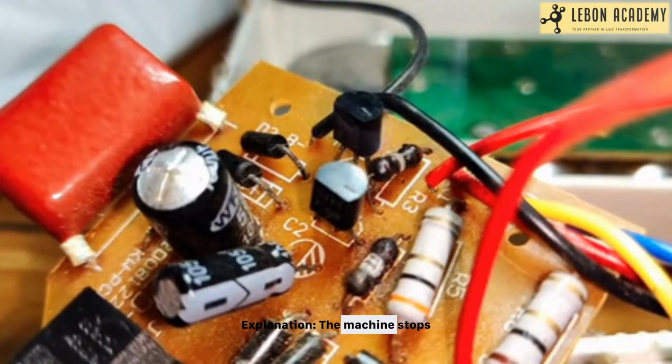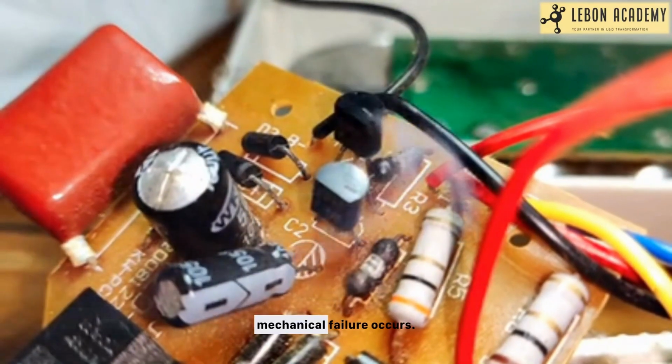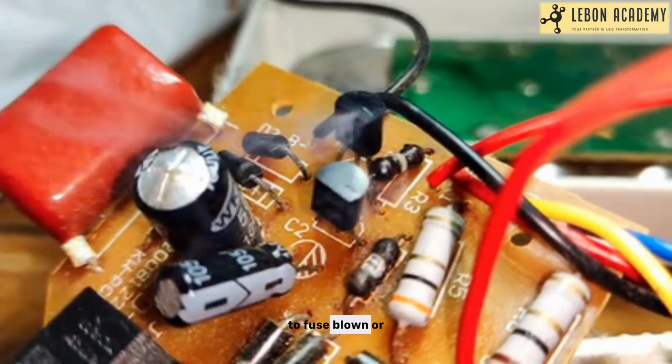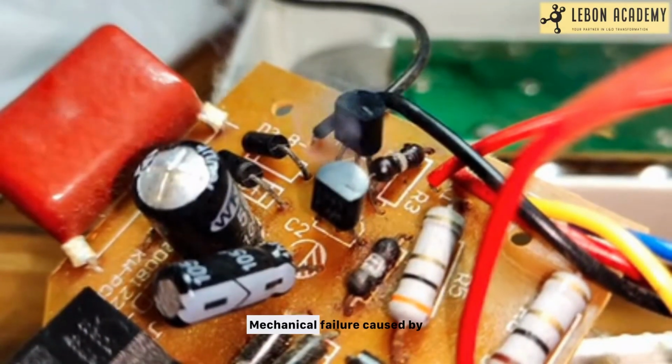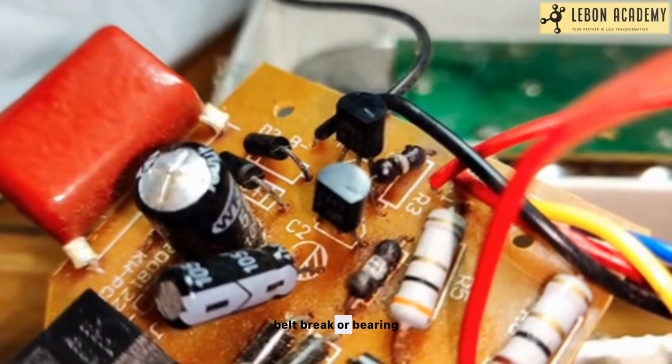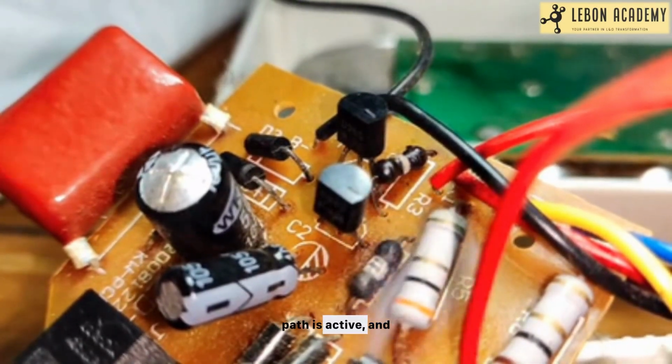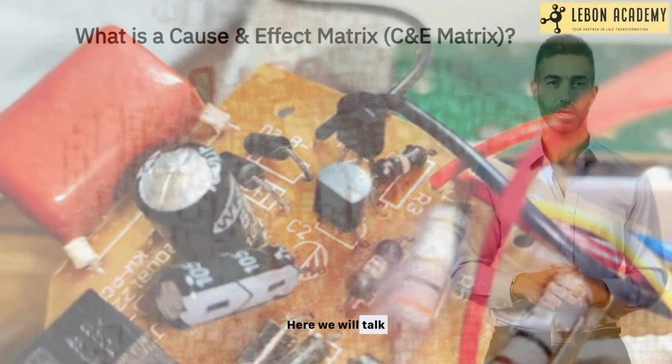Explanation: the machine stops if either electrical or mechanical failure occurs. Electrical failure happens due to fuse blown or power failure. Mechanical failure is caused by belt break or bearing wear. Next step: investigate which path is active and why. Here we will talk about cause and effect.